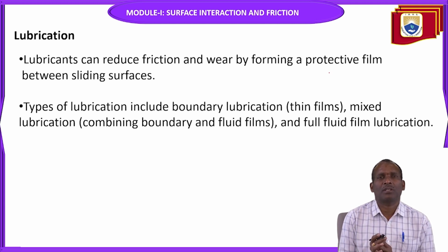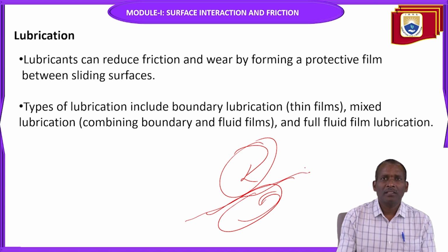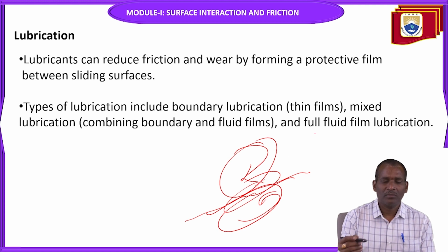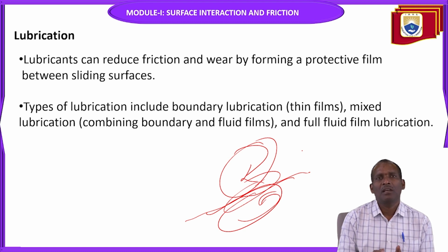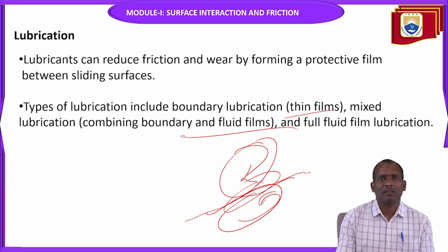Between these two surfaces, suppose two components are in relative motion like this. The contact of the lubrication is measured by the film coefficient, the lubrication film coefficient, which distinguishes thin film lubrication and thick lubrication film. The material scoring depends upon this thin film lubrication, the boundary and the fluid film thickness. So you can calculate this film thickness.